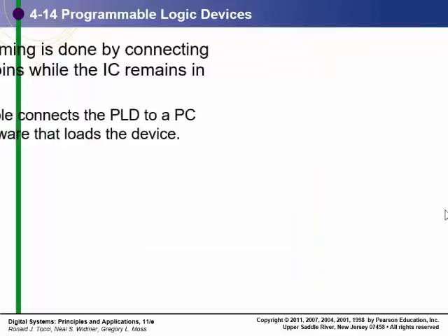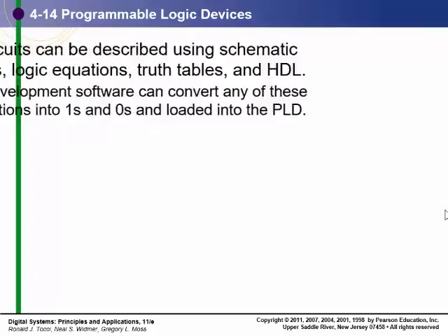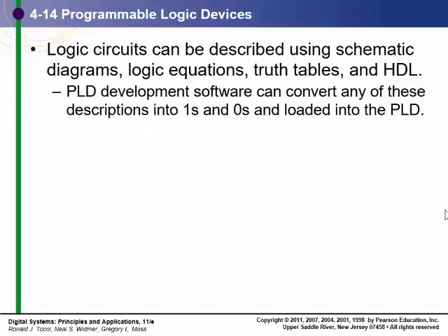So that's it. We're basically connecting to the 4 pins, the IC remains in the system, the interface cable loads in, and we can program this directly into the system. Now this is a development board. I should point out that when we design a PLD type system, we can design it with the programmer on the final system board, so it can be reprogrammed in the system out in the field. We can change the design out in the field, or we can leave those pins off. It's only 3 or 4 pins that are involved.